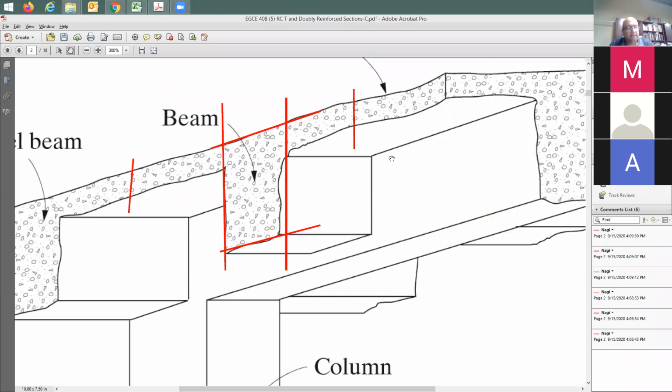I think the T is going to be stronger because it moves the neutral axis a little bit above the rectangular. Then the C is going to be smaller, so it's going to have greater resistance. You mean C lowercase, the neutral axis depth, right? Yes. All right, this is a very good answer.